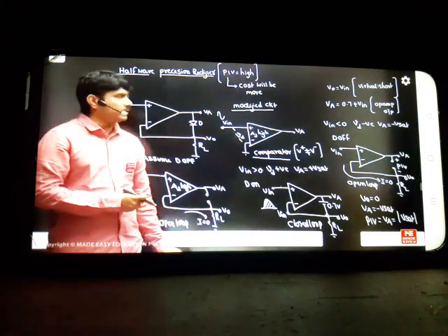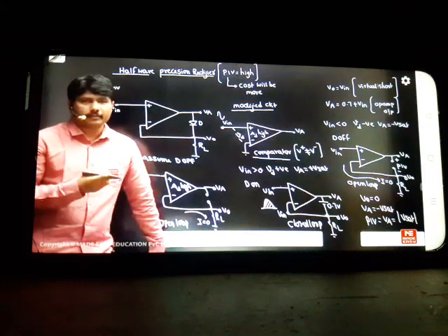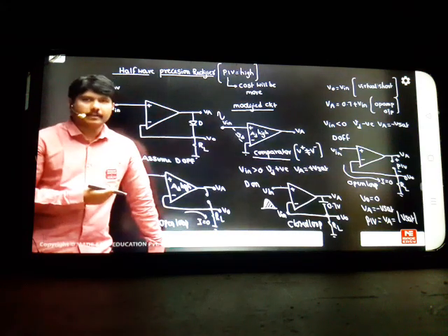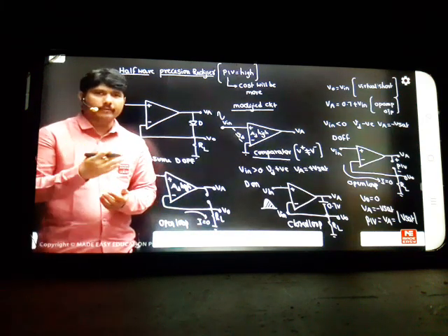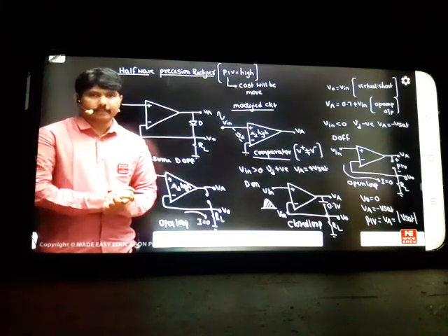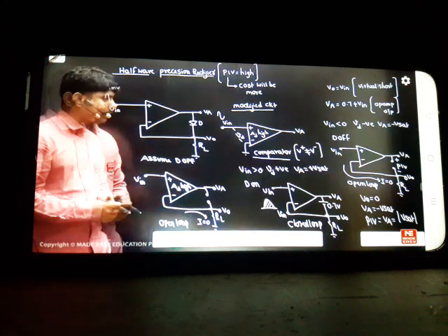When it goes, the cost of the diode will increase, so the system cost will increase. So today we have to propose a half-wave rectifier once again, in such a manner that the PIV is reduced. That is the next proposal I am giving you. This proposal is not a good proposal. Why? Because it is giving a PIV rating of plus V saturation. V saturation can be 10 volts, 15 volts, 20 volts. We cannot get that much PIV rating in diodes. So this is the main drawback of this half-wave system.